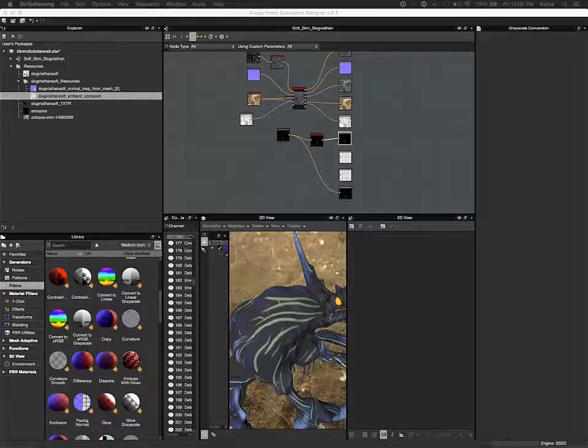Okay, Claude, so you are importing the model, right? So I've imported the model already. We have to have the model to work with, right? I've also baked a normal map inside of ZBrush, and everything that I've mentioned before. So yes, you absolutely have to import the model into this program to work with it to build your materials. I mean, you don't have to. You can work off a cube, but it makes it easier when you're actually looking at the model. And in the end, you will have to import it anyways, because when you bake everything out, it has to follow your UVs.